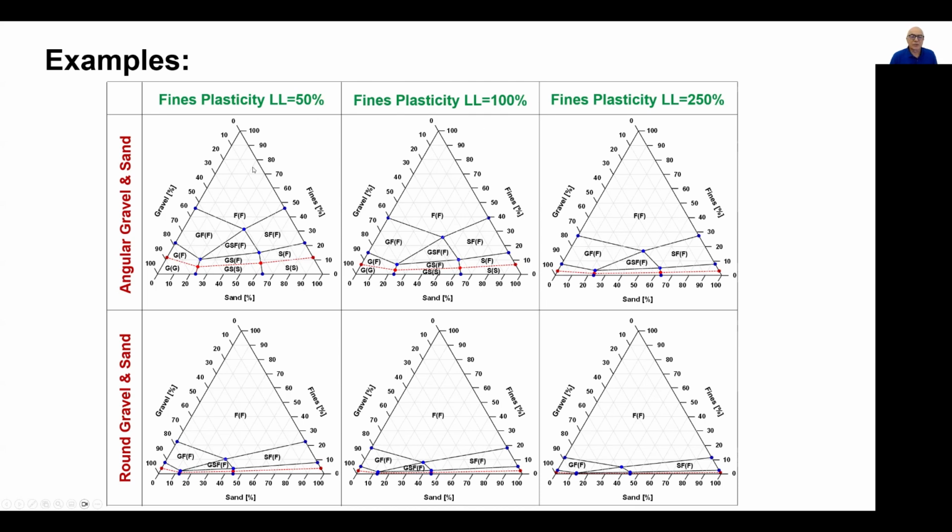And as we move to higher plasticity mixtures, the region controlled by the fines increases dramatically, and the effect on hydraulic conductivity, really just a very small percentage here, is about 4%. By 4%, you have already filled the voids of any sand or gravel when you use montmorillonite.